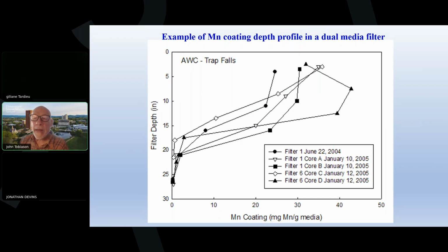I have the last one. William Denko says potassium permanganate in filters may not deposit. Can you go over this again? So potassium permanganate is a salt that dissolves in water. So it's permanganate. That's a dissolved ion. It's pink. It makes pink water. It reacts with reduced substances like iron or manganese or other things, and it becomes reduced, usually to manganese oxide itself.